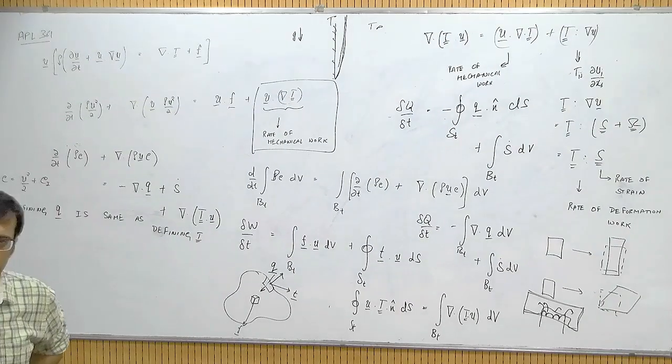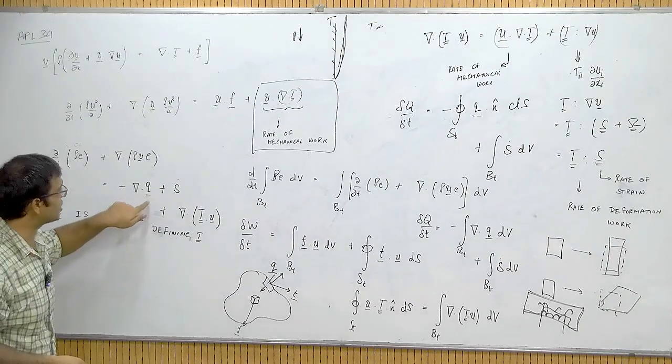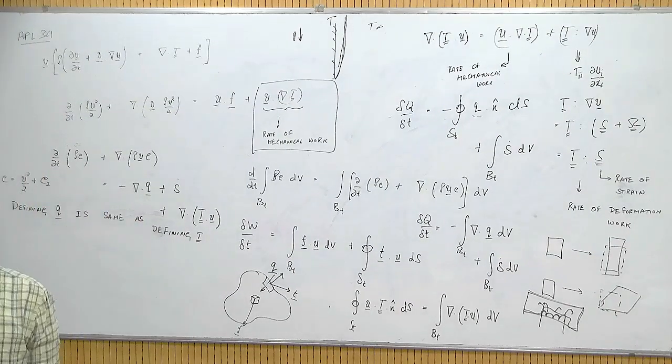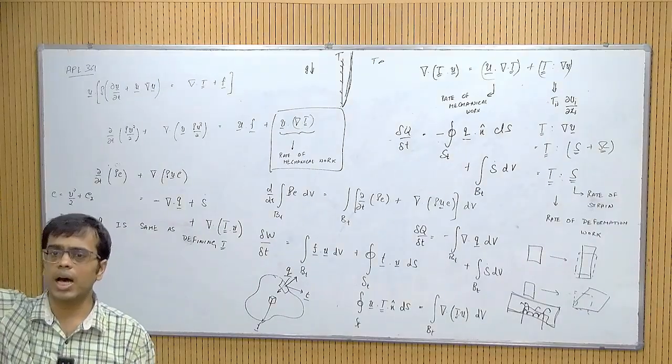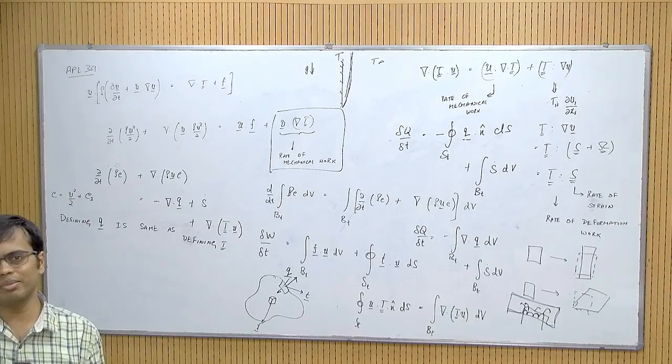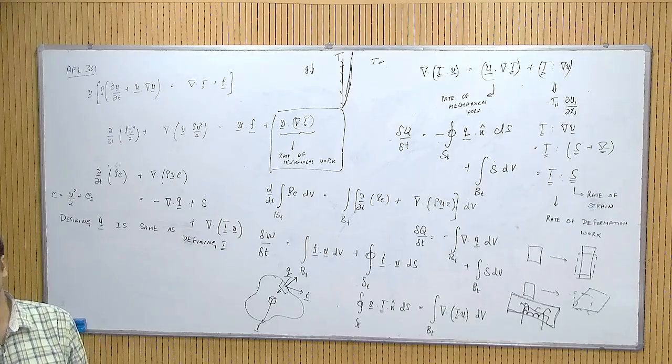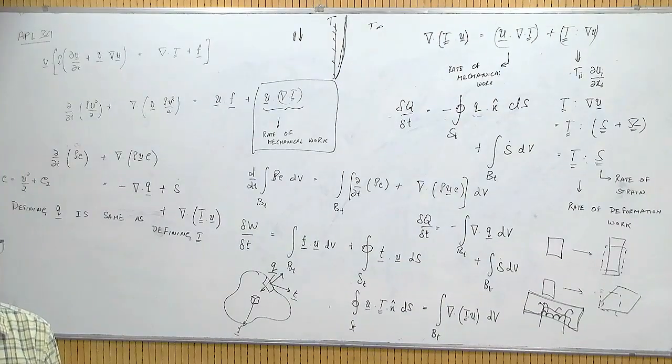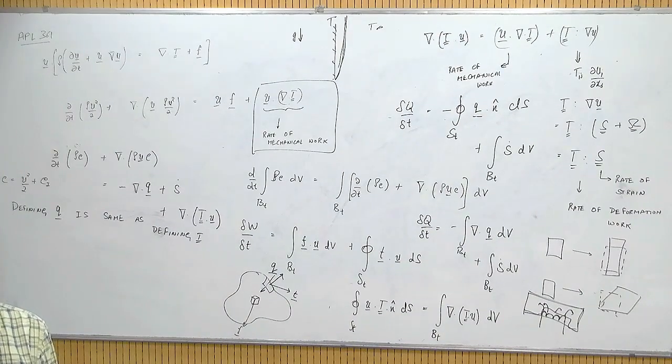Okay, the same things actually are responsible for this Q. You have particles which are vibrating at a higher vibrational speed and frequency, basically have higher temperature, and you have particles which are vibrating at a lower frequency or lower amplitudes, basically have smaller temperature. How does the information of this high temperature and low temperature propagate? It is through their transfer of momentum to other particles.